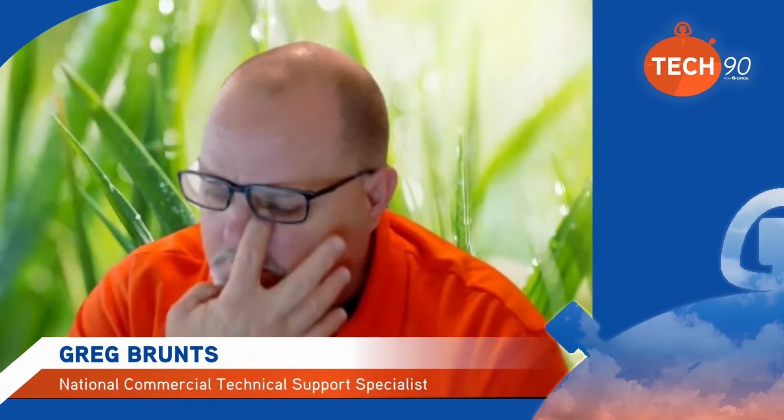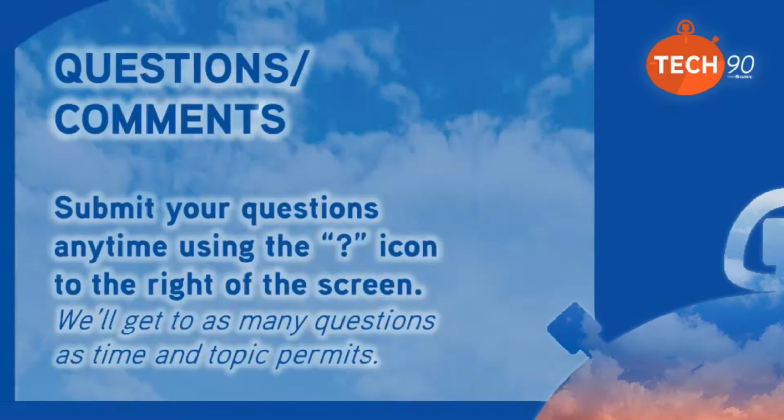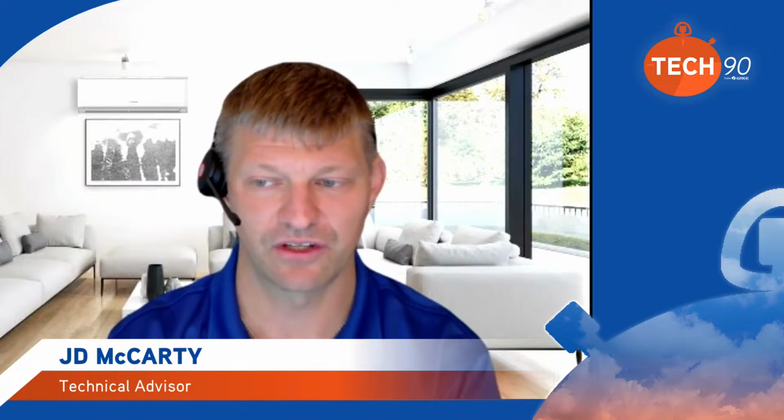Same as a mini split, though, they have one EEV, and it's going to cover your flow for cooling mode, and then the EEV is also going to cover your flow for heating mode. But I do believe it does show you what position that EEV is in on the mini split service tool. It's up to like 480 steps, but it'll tell you what step it's actually in. You can watch it open and close. The EEVs that Gree uses are from 0 to 480 steps.